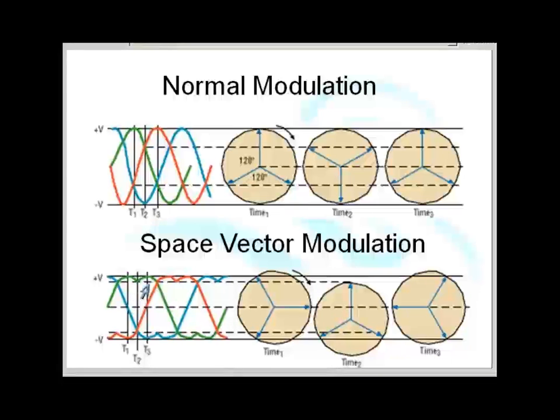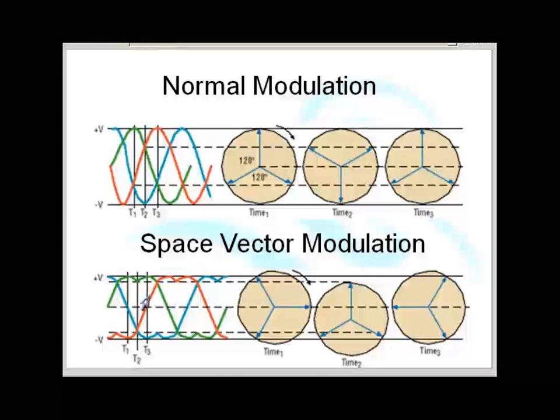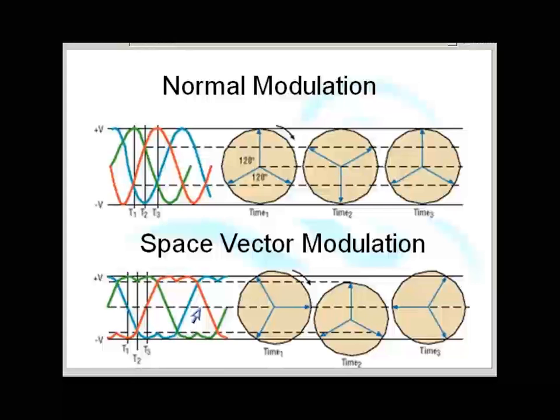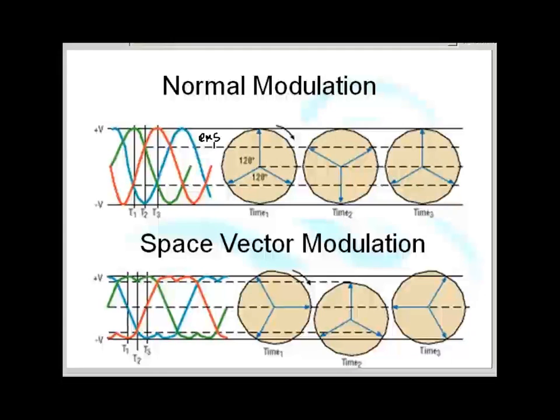The way we change the voltage is by stretching the waveform. So we stretch the waveform at the top end, or if we want to reduce the voltage, we squash the waveform up at the top end. Because we're able to create basically whatever wave we want, we can change it from a sine wave to a slightly stretched out sine wave. And when we change it from a sine wave to a stretched out sine wave, the RMS value, the root mean square voltage value, goes up and comes down.